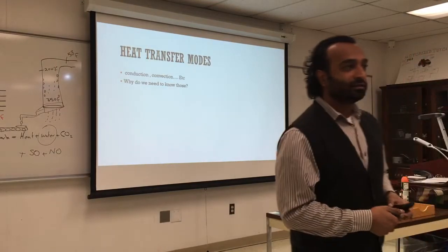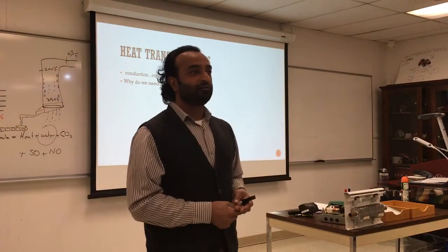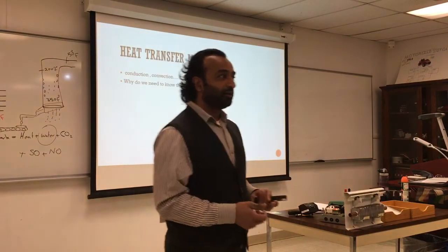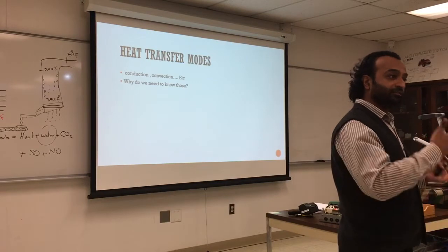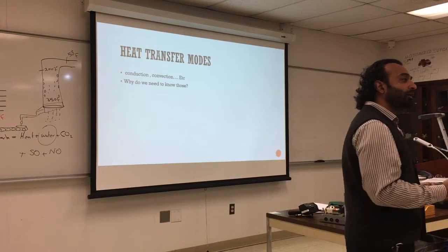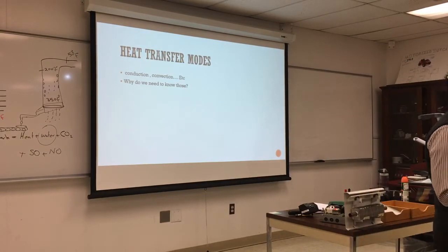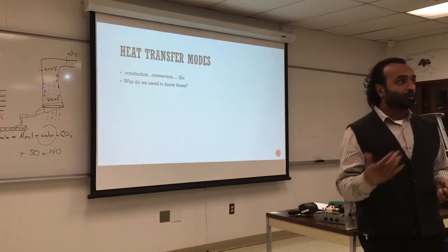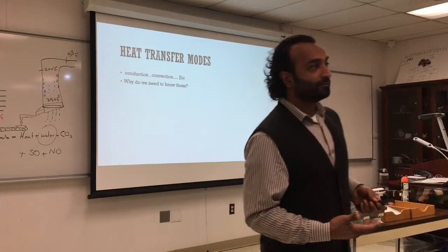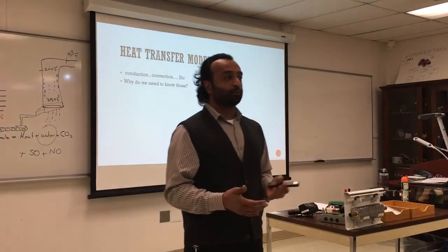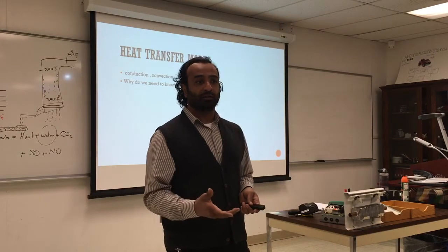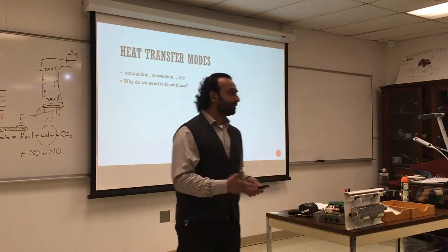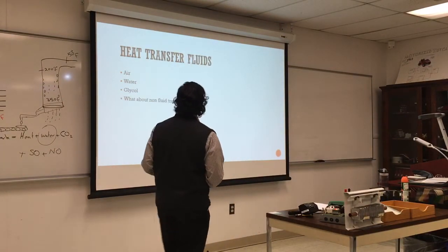We also talked about the difference between a regular oven and a convection oven. So a regular oven uses natural convection. There is no fan in it. The heat will rise and fill the whole oven. Meanwhile, a convection oven is very quick. What it does is it circulates the air around the cavity of the oven. Even though it's smaller, it heats up quickly. The air fryer, same thing. Very strong heat element, and hot air circulating quickly around the food.